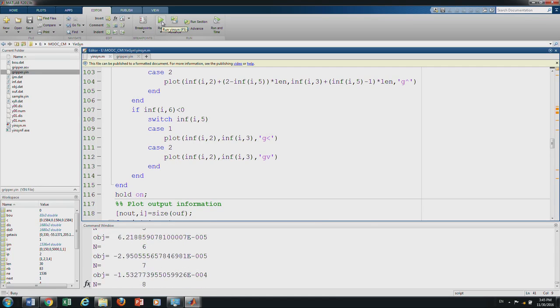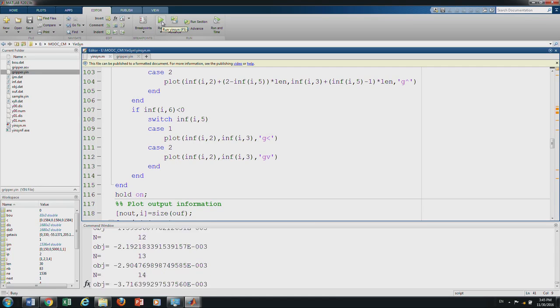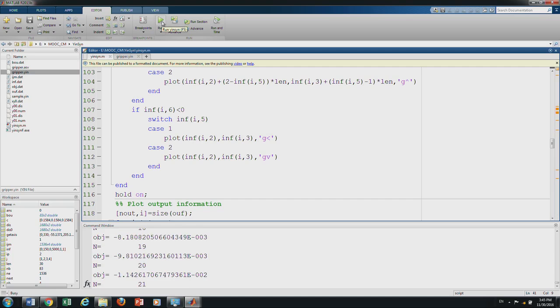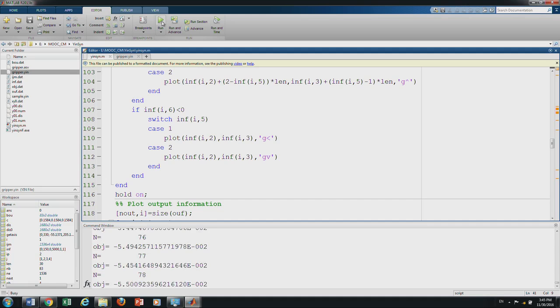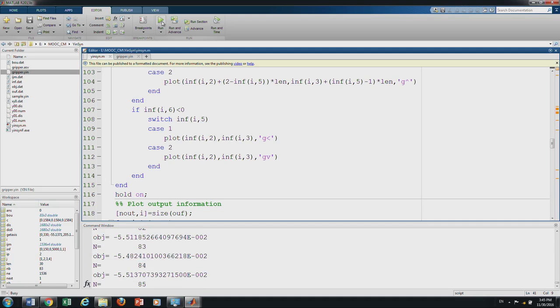And we will run it with finer discretization. We changed the volume and saw that there is not much effect in terms of topology. Now, we can also make it finer and finer, where it will be so fine that you can take it and 3D print it today. Okay? That is possible to do. You just have to do image processing of this and 3D print. That was the idea with topology optimization. You do not have to give the algorithm anything other than the specifications, it figures out everything, gives you a solution.